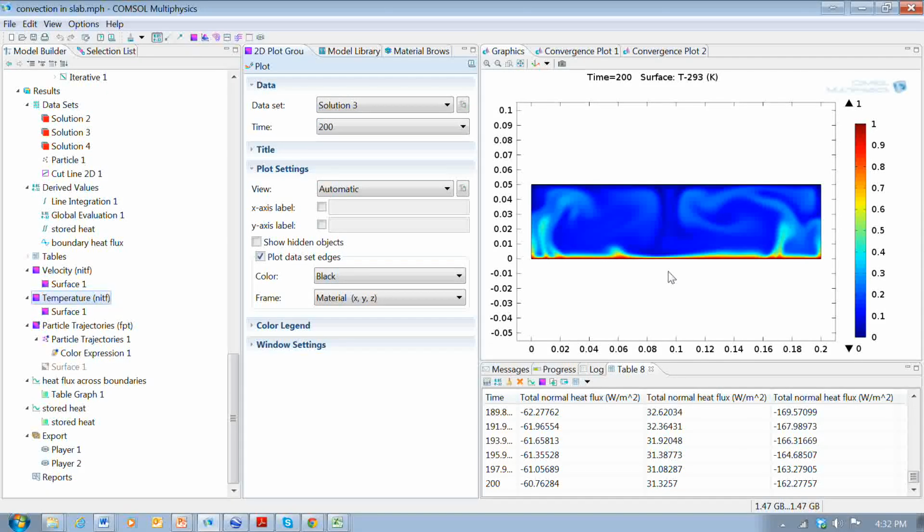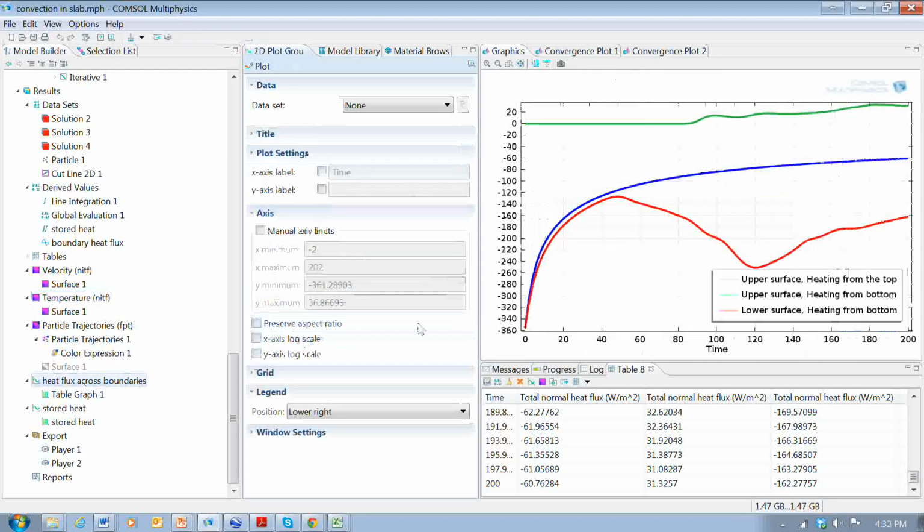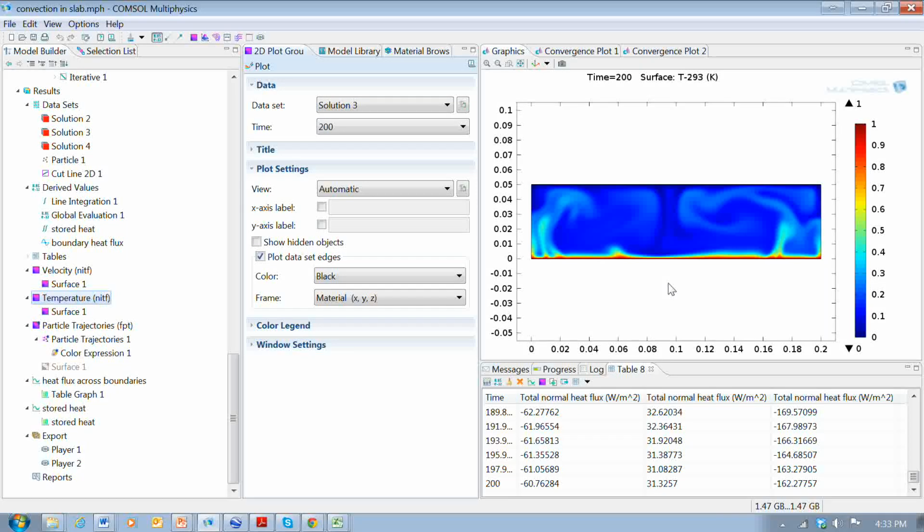Air, as it turns out, has pretty low thermal conductivity, but the problem is if you have a layer of air, this natural convection occurs, and the natural convection transports heat, just like we see here, and like we see the elevated heat transport shown by these graphs. And so that's why just a gap of air is not the greatest of insulators.